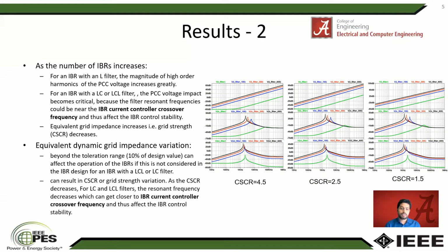And another one, I already explained that as the short circuit ratio drops, the resonant frequency for LC and LCL filters gets closer to lower values.